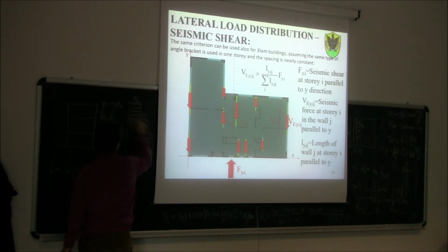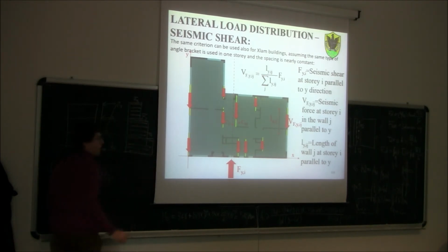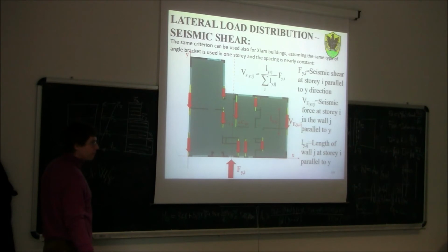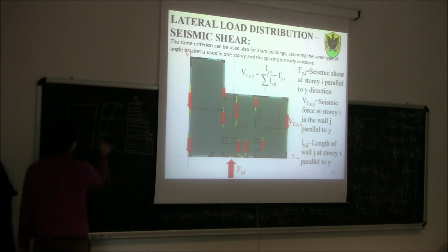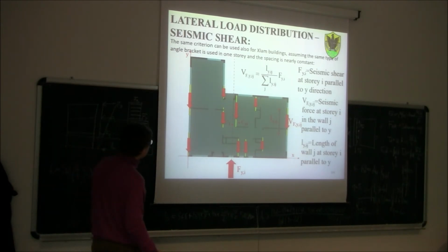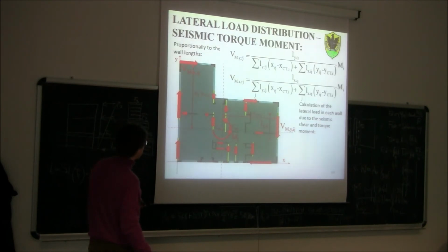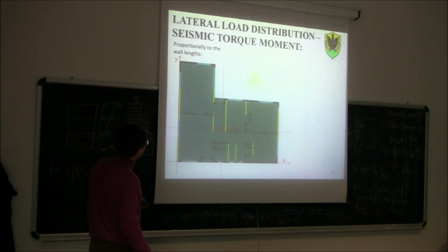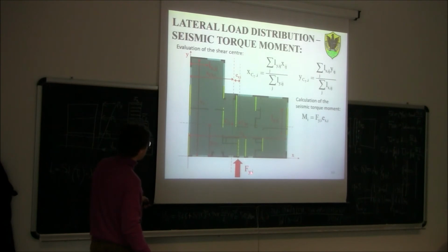So this is the story shear. And then at a certain story, for example, at the base story here, I have the total shear, and the total shear would be, for example, Fy1, so this Fy1 will be the total shear at the base story.